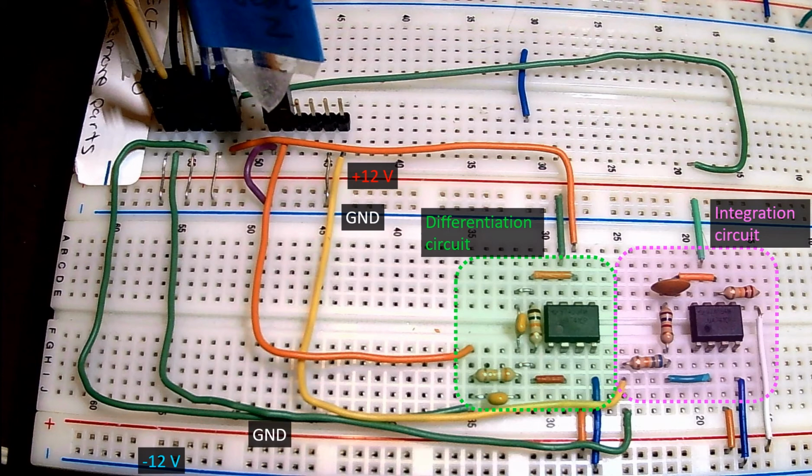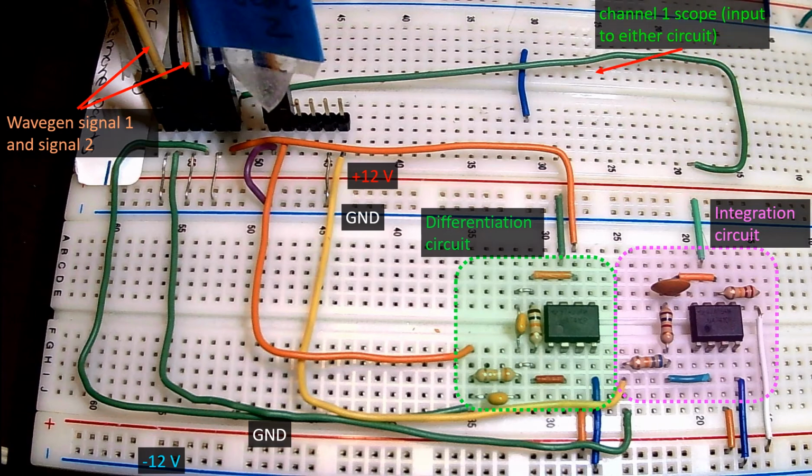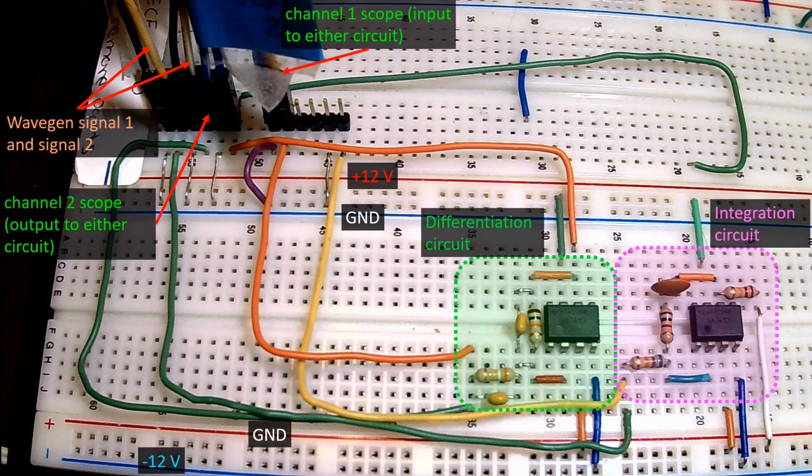For use with the AD2, the WaveGen signal 1 and signal 2 can be used as the inputs to the differentiator or integrator, respectively, or vice versa. Both scope channels are used to monitor the input and output of each circuit. Given only two channels, only one circuit can be measured at a time.